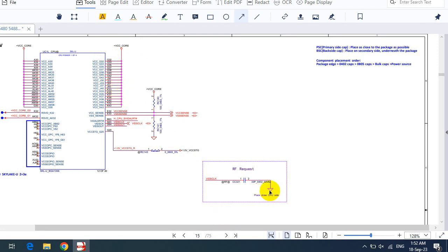Here this is a ground, but there are 2 types of ground. This is basically a digital ground, and there is another ground that we call analog ground. Of course, there is a chassis ground and others, but on the computer motherboard you will find just digital ground and analog ground, and sometimes a chassis ground.